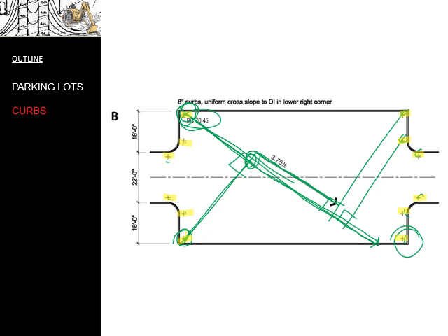And again, that process is based upon recognizing that if you have a 90-degree angle along a line, any point that is perpendicular to that will be the same elevation as you would achieve if you simply calculated directly along this line.